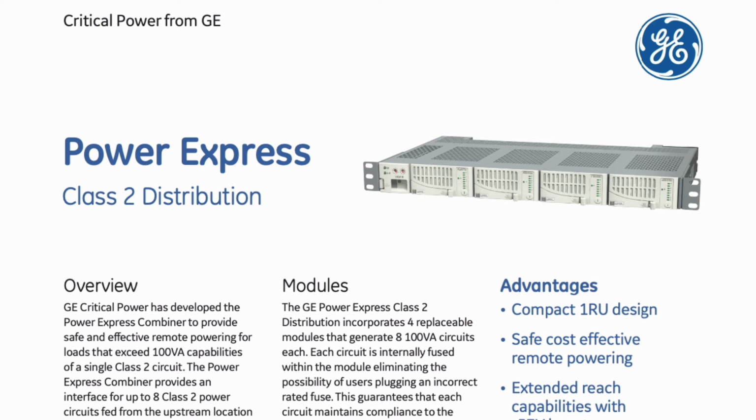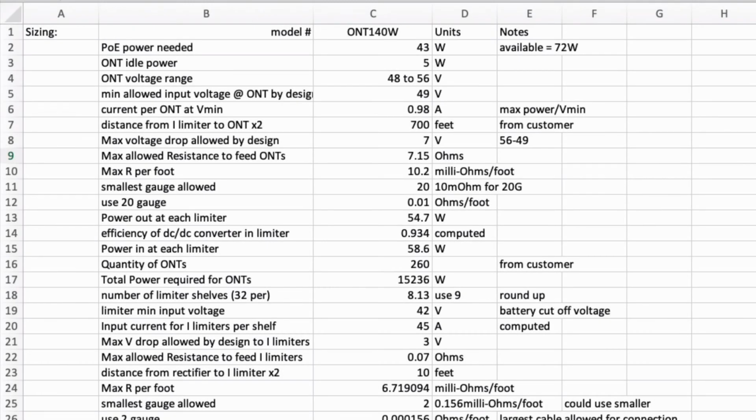It has 4 power modules, each with 8 100-watt power limited outputs for a total of 32 outputs per shelf. Back on my spreadsheet, I figured out that I need 9 shelves of power limiters to supply the 260 ONTs asked for.